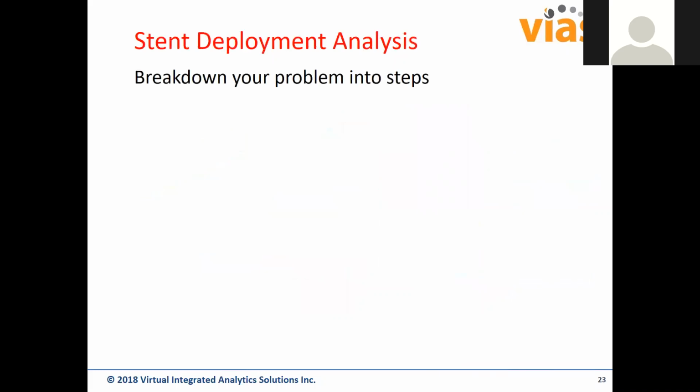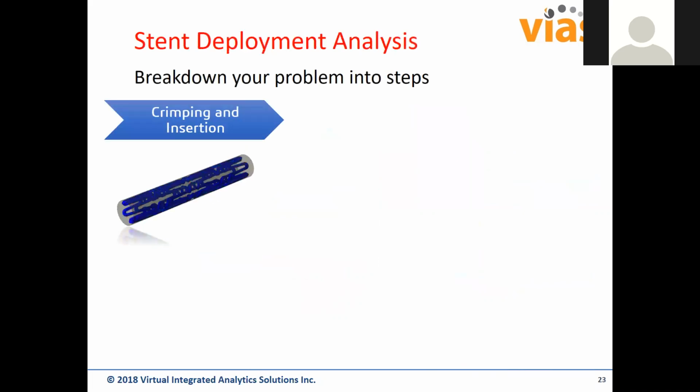So what we talked about initially was the ability to break down your problem into simpler steps, or like in this case, we have the problem exactly the way it would go through in nature. So the stent is installed by crimping and compressing it and inserting it through into the blood vessel. So we take this stent CAD geometry and we create a finite element model and run simulations under the applied loading.